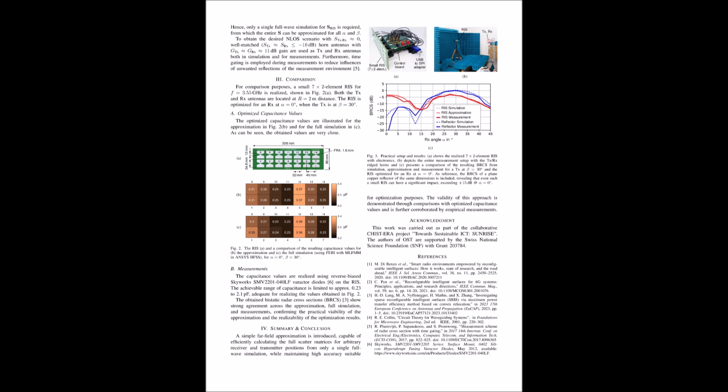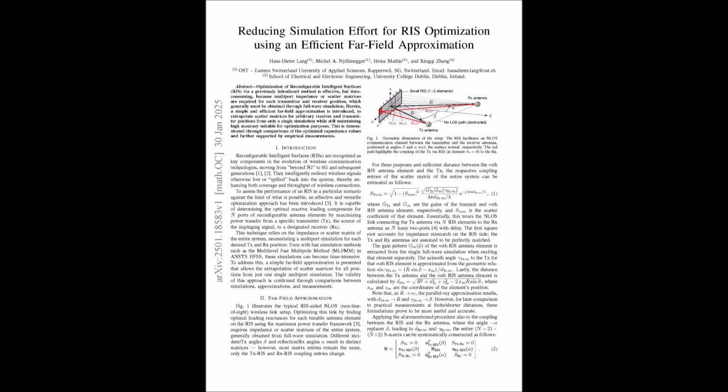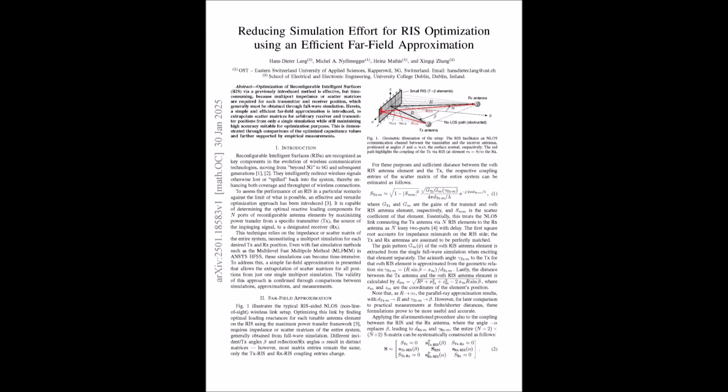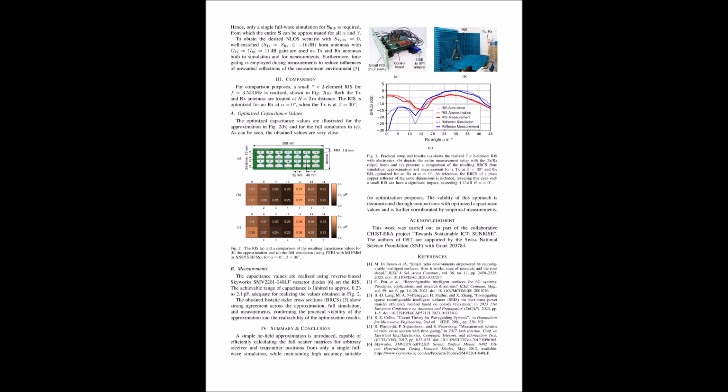And that's why the phase information is so important. It determines how those signals from different elements on the RIS will ultimately combine at the receiver. So the RIS isn't just reflecting signals, it's intelligently manipulating their phase to ensure they combine constructively. Exactly. It's about orchestrating those waves to maximize the signal strength at the receiver. And that's the real power of RIS. It's like a tiny conductor leading an orchestra of electromagnetic waves.